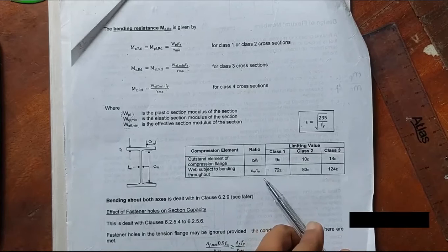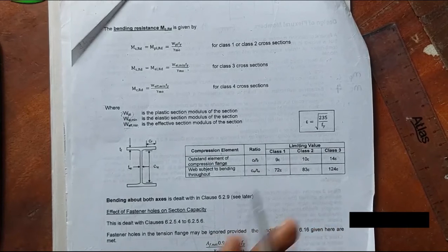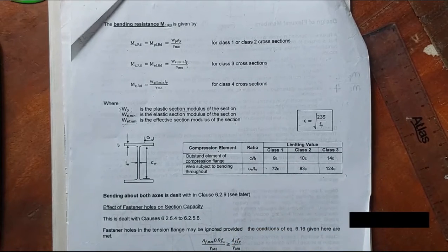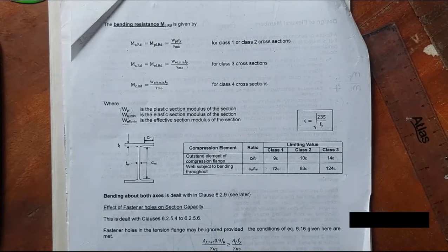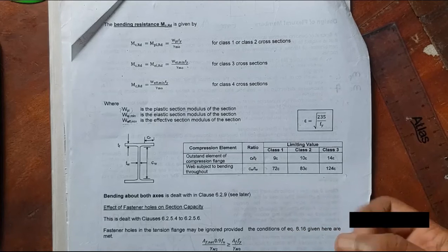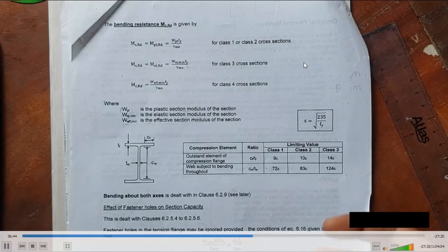Let's say web and flange are both class 1, so your member is class 1. Let's say one is class 1 and another one is class 3. Then class 3 is weaker, so your section is defined as the weaker one, and your overall class is also class 3. And likewise, in these design cases they give you the direction. They give you the bending resistance or the shear resistance based on your section. You just need to adapt it and calculate